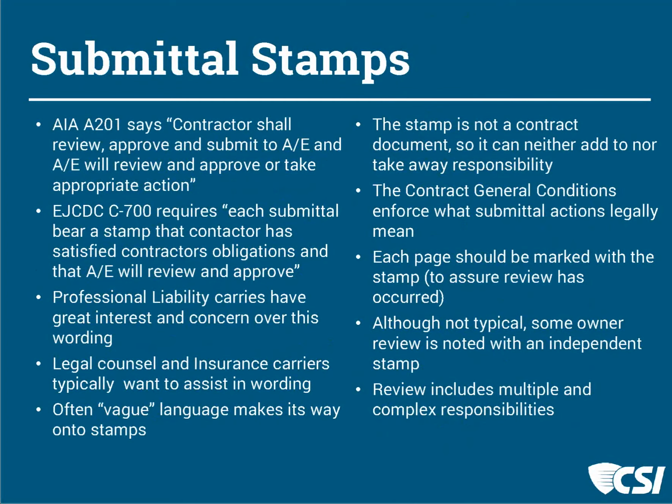The stamp isn't a contract document, so it can't add to any responsibility, but it also cannot take away any responsibility. Your responsibility and liability with the project lies within the contract documents other than this stamp. That stamp is not that. So the general conditions enforce what is required legally as far as what a submittal means, and that's where the meat of the responsibility and liability lies.